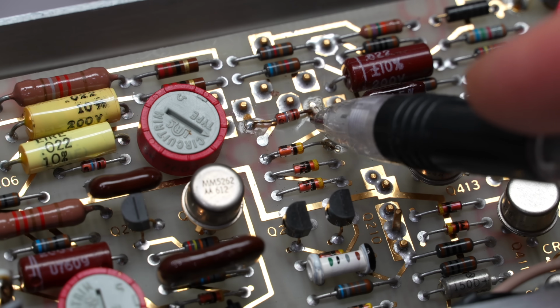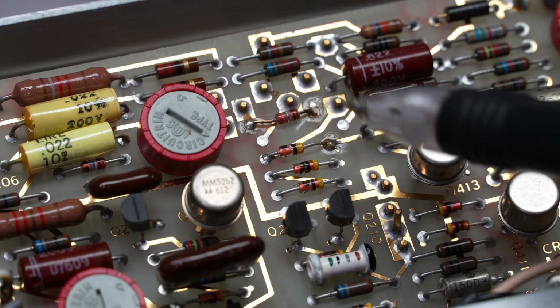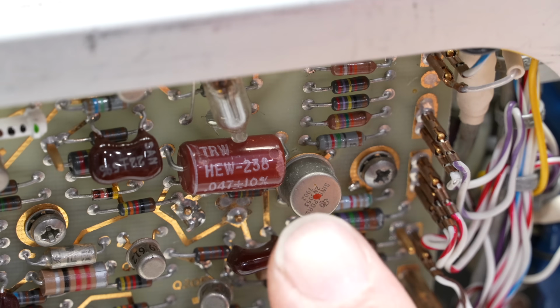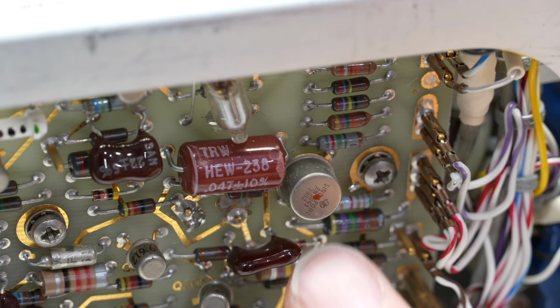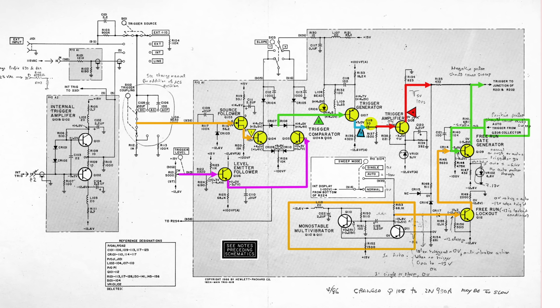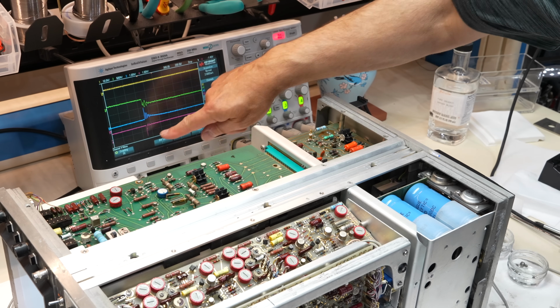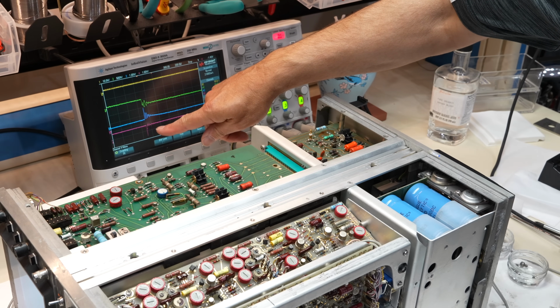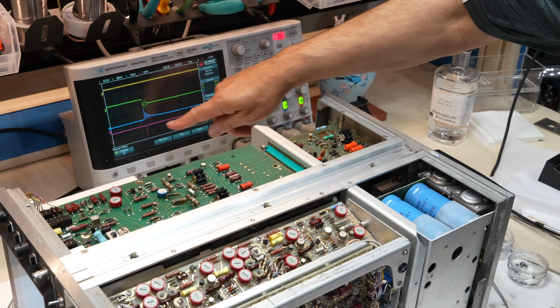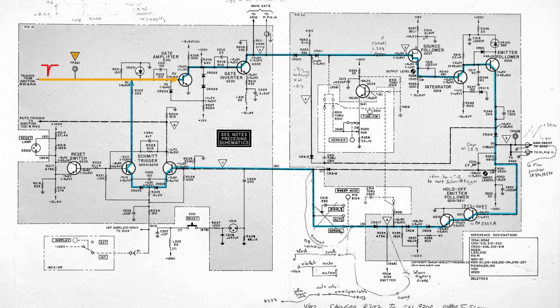So far, we removed a shorted diode that did not exist in the schematics, repositioned a smashed transistor, and verified that the first page of the triggering system did work as intended, delivering the required sharp triggering pulse to the second part of the schematics that is supposed to generate the horizontal sweeps. That circuit is arranged in a large loop with a few sub-loops, and we are now convinced that there is a fault somewhere in the loop.